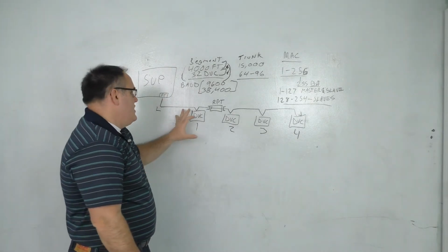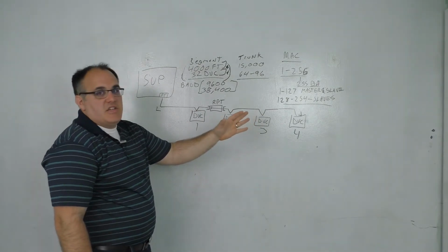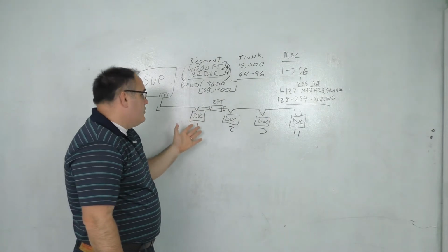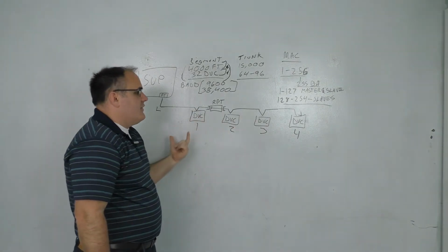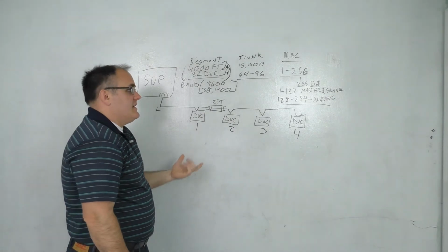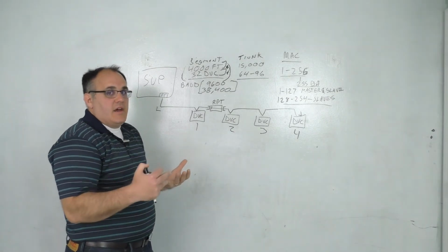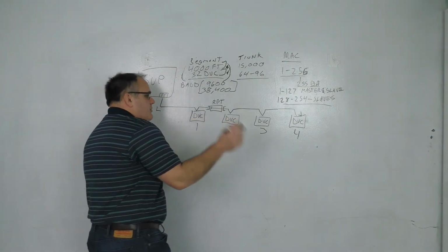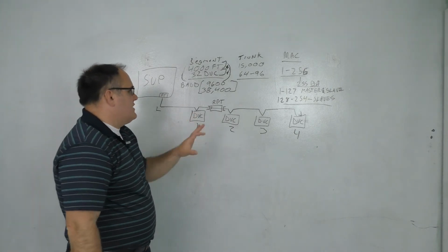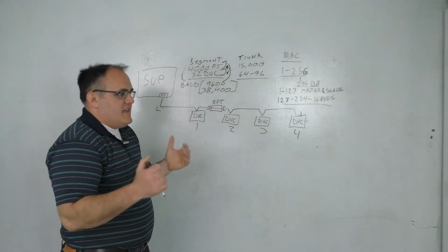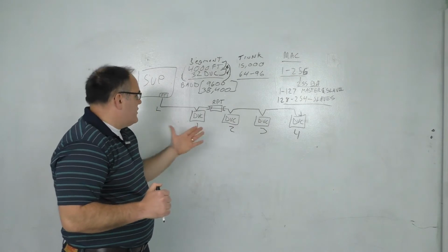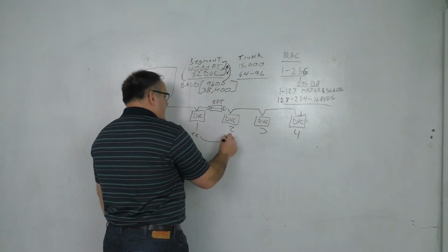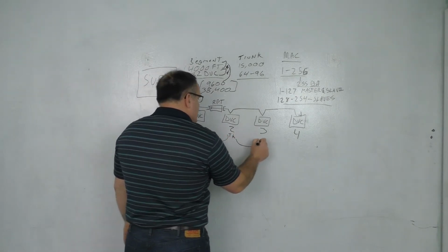amount of time. What that means is it can send out its initiates for its services, and that allows the device to initiate service requests, and it can then add its data to the messaging. That avoids collisions, because if device 1 and device 2 were communicating at the same time, since this is a serial network, it would cause data collisions, and that would be bad. So to avoid that, the token passes, and we'll just call it TK, from device to device to device.